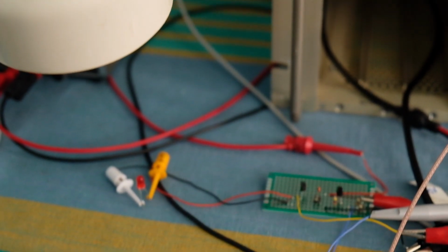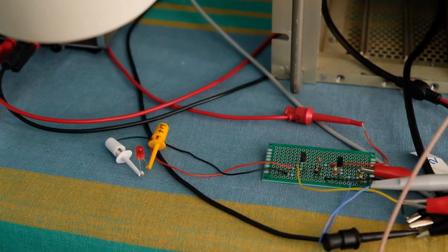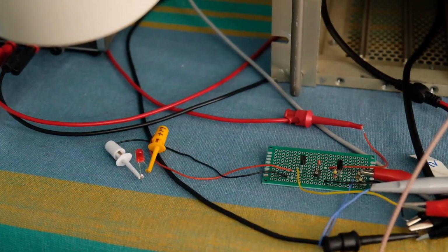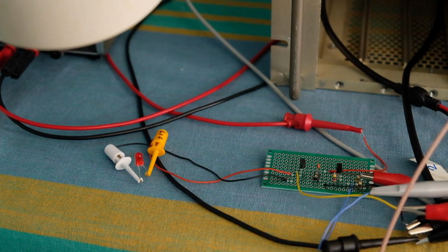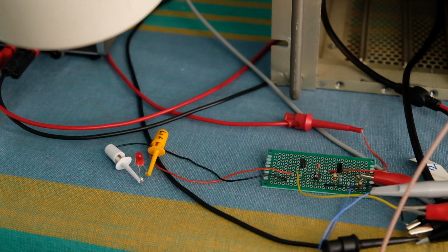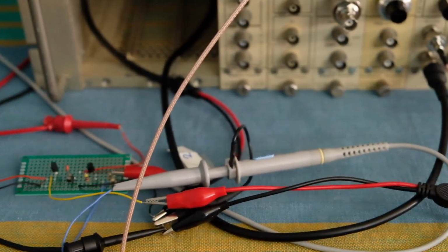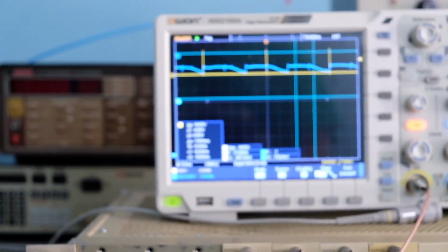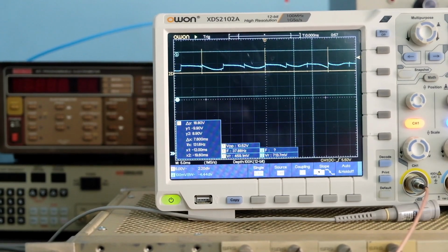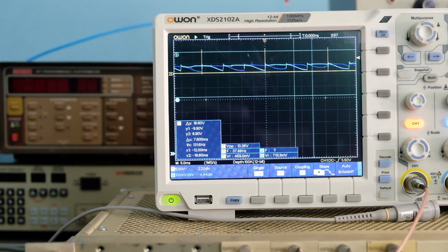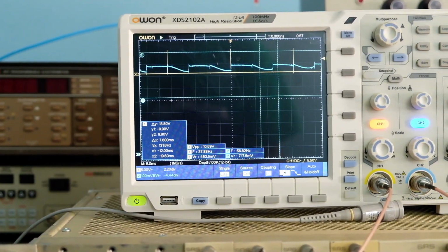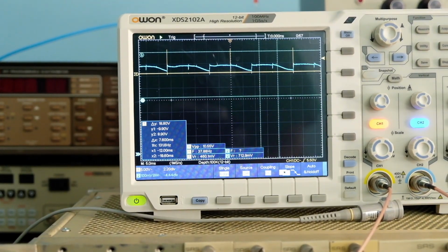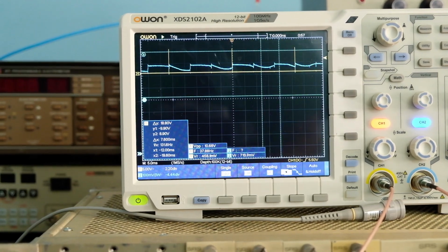Right now there's no light here, but I'm actually using a flickering source, which is derived off an LED lamp, so it's going to have some frequency related noise on the light itself. And right now with the light off, you can see there is a considerable amount of ripple, in the neighborhood of 60 Hertz I believe, which is just coming from the ambient light.